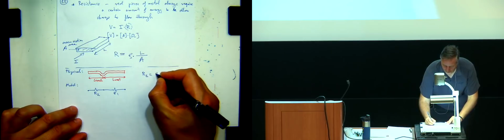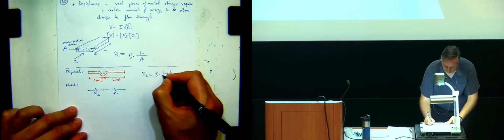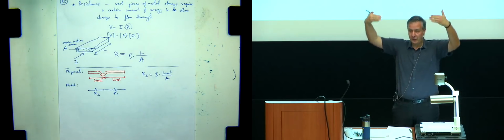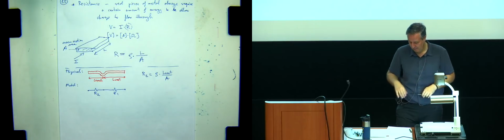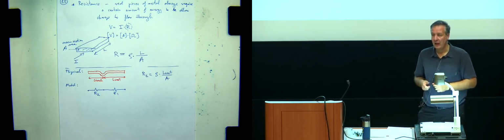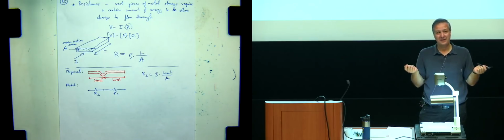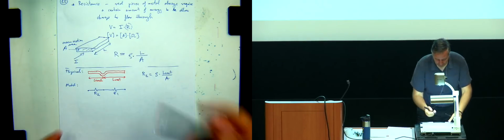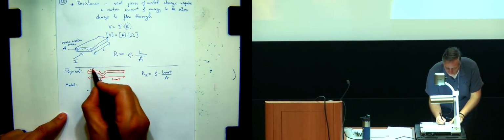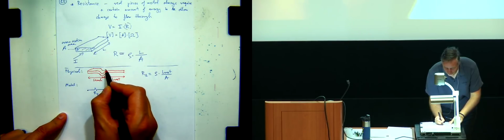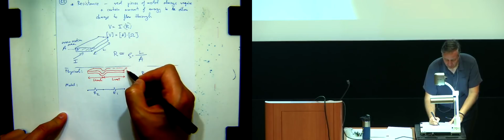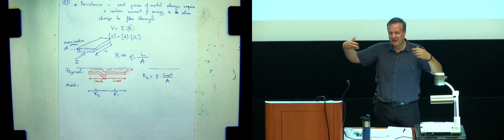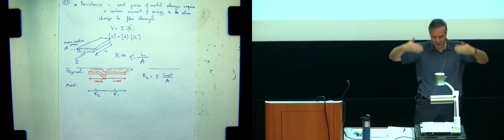Yep. So it will be rho times L rest over some A. I didn't specify A here, right? Because we're looking at cross-section. Yes? Okay, so the question is, would we specify A? As you'll see in this problem, A and rho don't matter at all. But just to give you an idea, this actually should look something like this, right? There is always some A involved here, right? But since we're doing a one-dimensional case, I'm kind of ignoring it a little bit, right? It's just a cross-section.